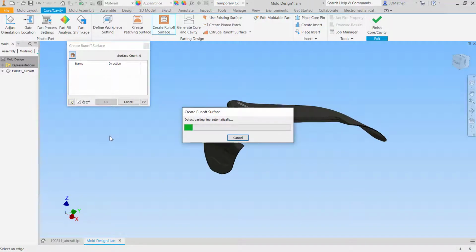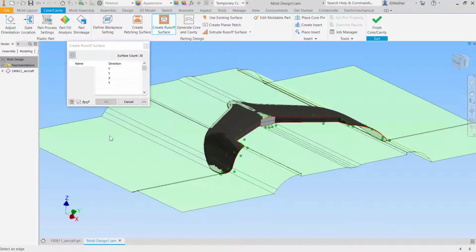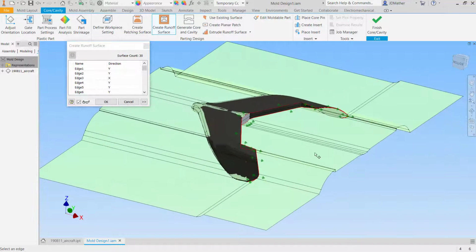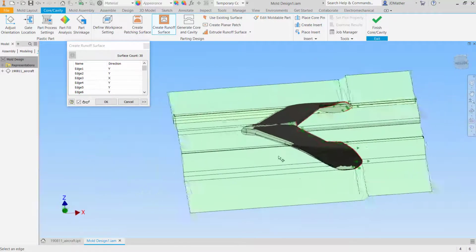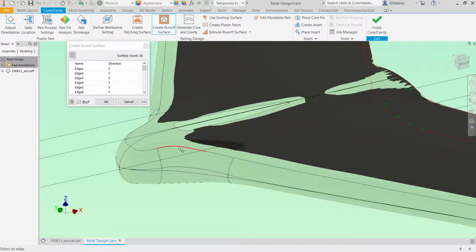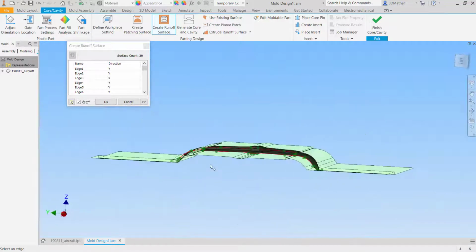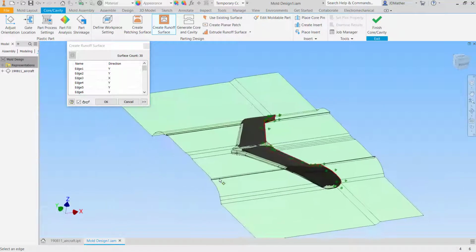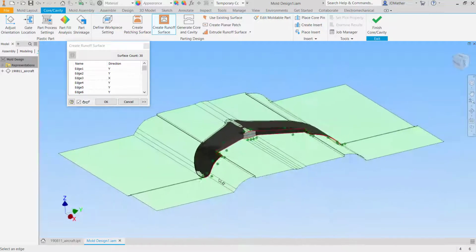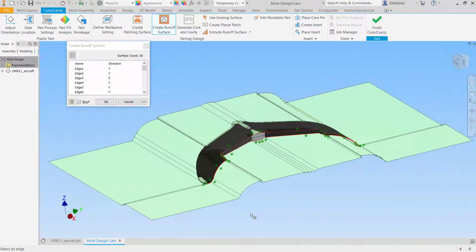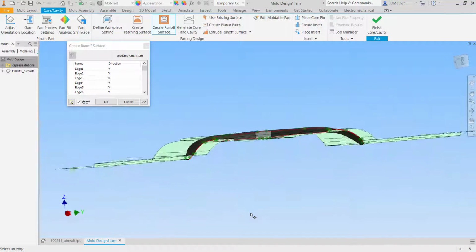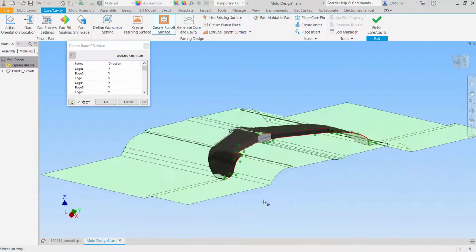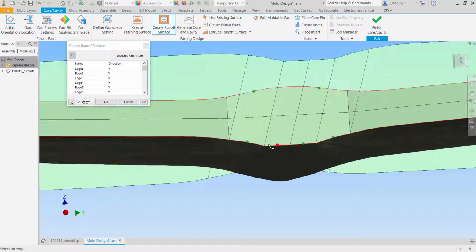And if it had been modeled with the design intent for manufacturing, all of these surfaces would automatically come off of the parting line correctly. We can see up here though that it doesn't come off the parting line automatically. So I would go back to the original design and consider the design for manufacturability. And actually I see that this didn't come off the parting line either.